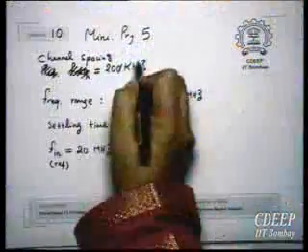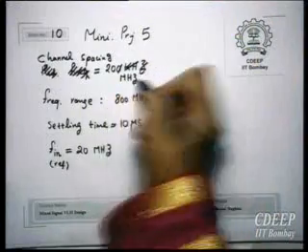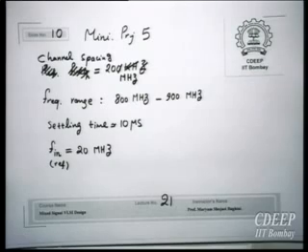Because this is essentially for, say for example, some digital applications. Usually, for wireless transceivers, this spacing is very small because their channels are very close. They don't want to waste bandwidth. But here it's fine. It is just a matter of learning, so it's okay. So you use a conventional divider with 20 megahertz spacing.